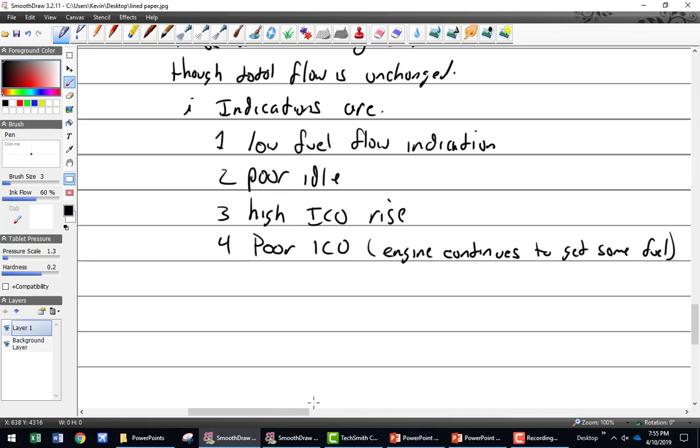So with the RSA fuel injection system, as I give it more throttle, I'm going to get more air metering force. The air metering force is going to want to open the servo valve, or poppet valve if you want to call it, which is going to allow more fuel pressure and flow to go through the poppet or servo needle out to what comes next? Flow divider, where it has what inside of it?